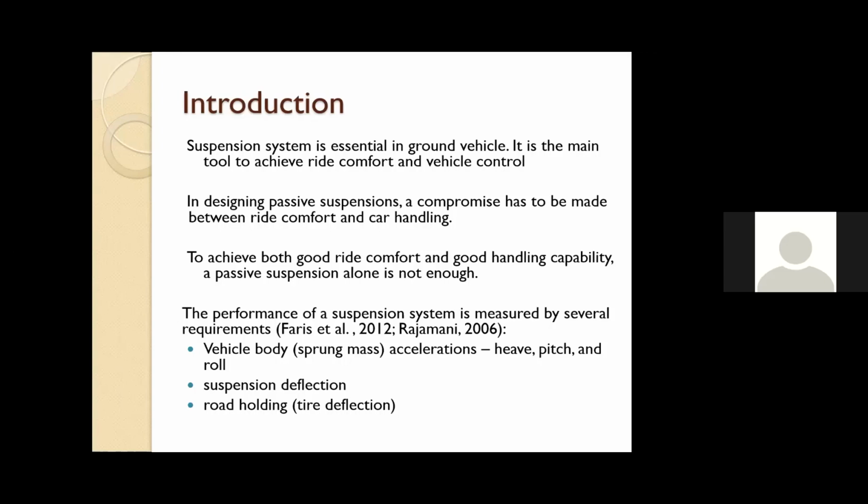Unfortunately, in any design of subsystems of a car, the ride comfort and car handling are not really working hand in hand. So if you improve the car handling too much, the ride comfort will be a little bit problematic. If you improve the ride comfort too much, also the car handling will be a bit problematic. So usually in any design of cars, we have to compromise between ride comfort and car handling.